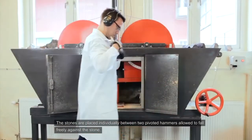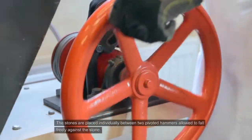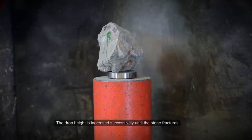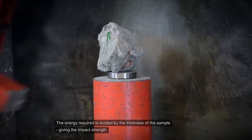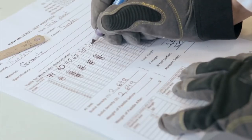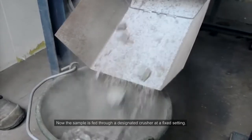The stones are placed individually between two pivoted hammers, allowed to fall freely against the stone. The drop height is increased successively until the stone fractures. The energy required is divided by the thickness of the sample, giving the impact strength. Now, the sample is fed through a designated crusher at a fixed setting.